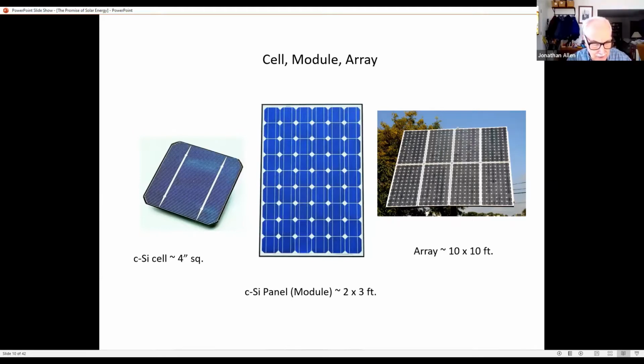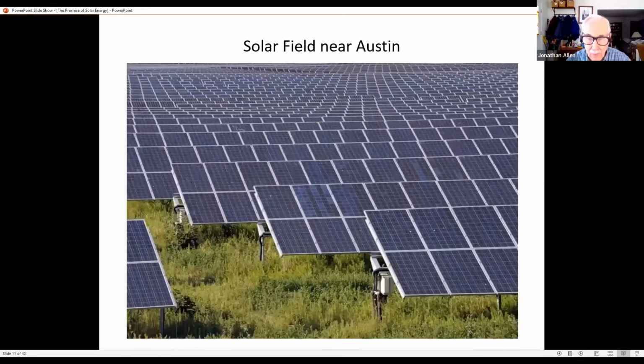Now, the efficiency of a photovoltaic cell is the amount of electric power it delivers per unit of light power striking the cell. Just as with any efficiency, it's what you get out divided by what you had to put in. Testing is usually done under an intensity we call 1 sun, which is, by convention, 1,000 watts of light power per square meter, measured at the device's peak power point. Peak power point?